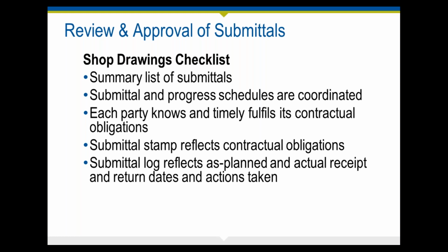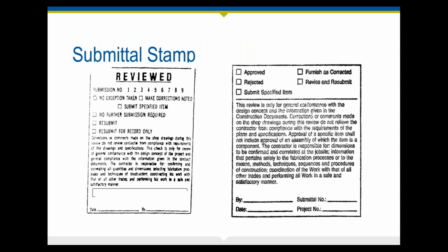And that finally, you have a submittal log that reflects as planned and actual receipt and return dates and actions taken. So that if there's something that comes up later about the amount of time that it took for you to review shop drawings, you need to be able to go back to your log and actually show what it is that you provided to the contractor and how that compared to your contractual obligations and so on. So that submittal log can be very important.